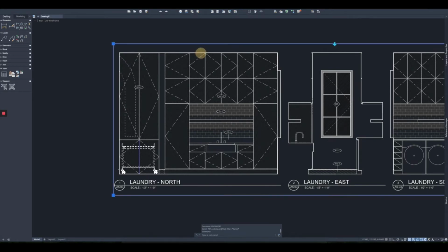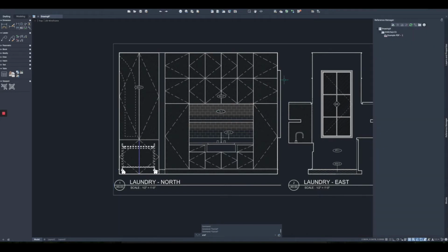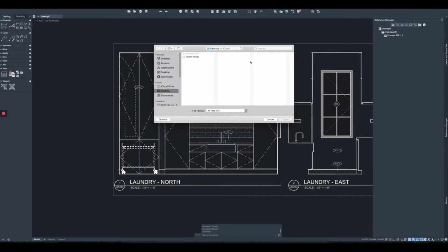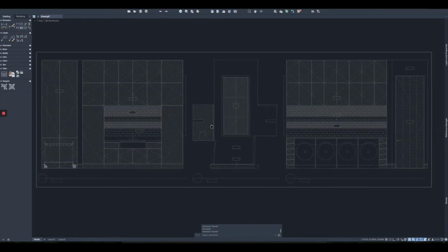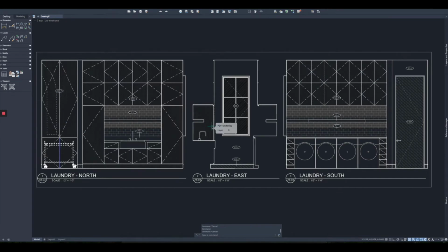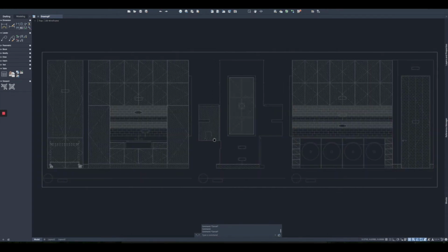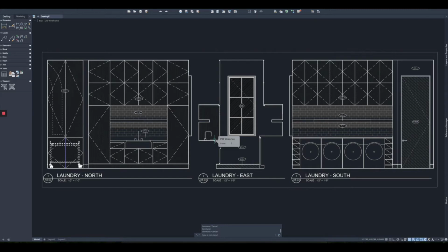Whereas this is an XREF, and it's inserted just like you would insert any other XREF using the XREF command, or opening up the XREF window and then going over here and telling it that you want to insert a file. So when this is inserted, it's going to be brought in to scale. So it's important to understand that anything that's been drawn to scale, when it's printed, it's going to be reduced uniformly in size so that it fits in a given sheet.